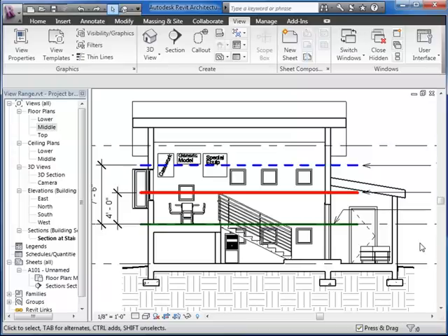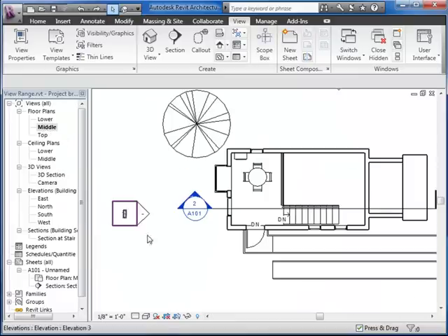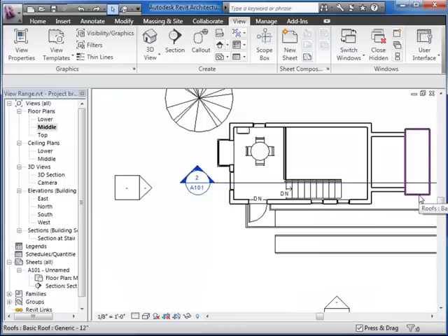You'll notice that we are cutting through windows in a variety of locations. We're cutting through walls. We're looking down on furniture, railings, and stairs. And we have a few items that are occurring up above our head. Furthermore, we're cutting through this small piece of roof over here. Some of these other items down in here are actually occurring below the bottom of the view range. But we have this double height space down in this area here, which we may want to include in the view itself. So let's return to the middle floor plan. As we said, here's the roof that we're actually cutting through.